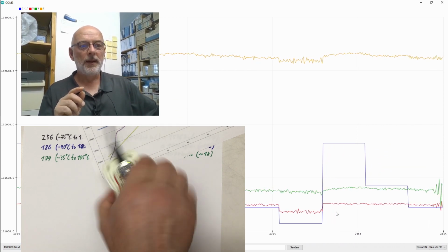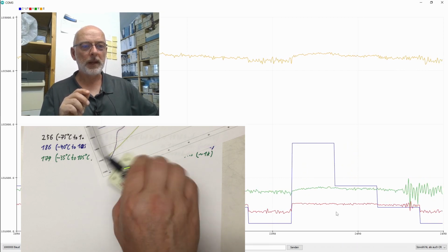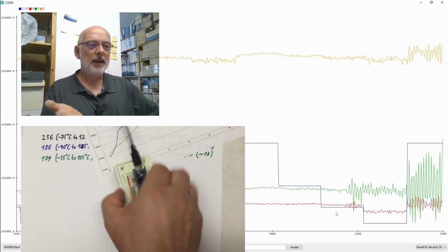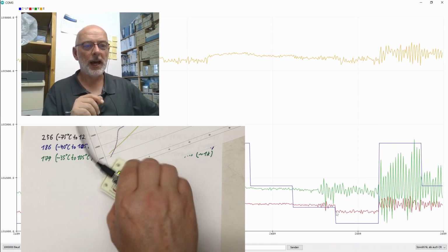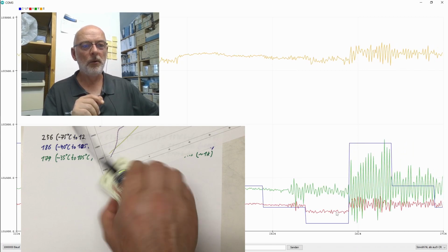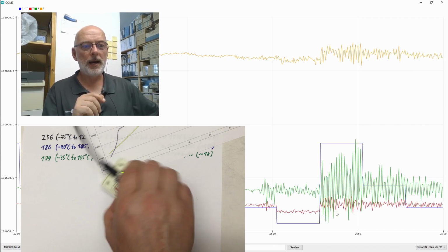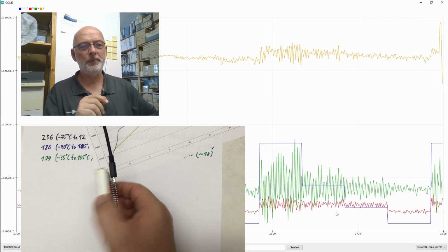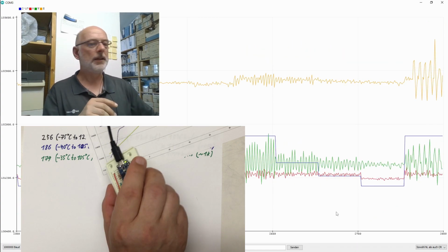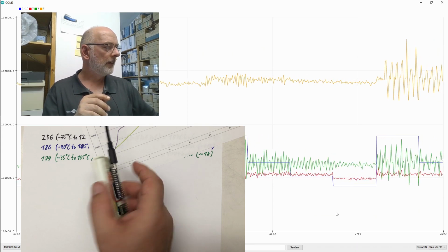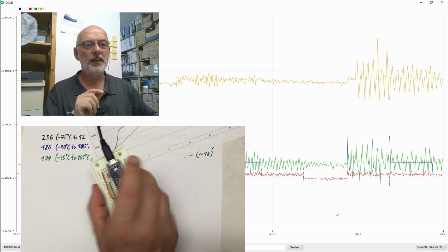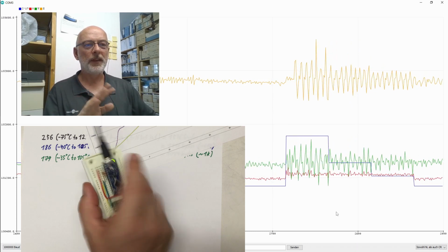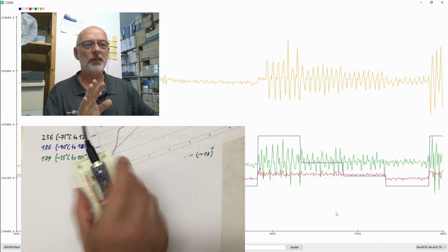And now let's do some movements. I try to be consistent. At minimum bandwidth, we have, of course, the largest errors, and then the errors go down indeed. But I fear, depending on the axis, even at the lowest, I'm moving it now in another direction, even at the highest bandwidth setting with only 500 microseconds delay, we still have errors that are far, far beyond the noise level.